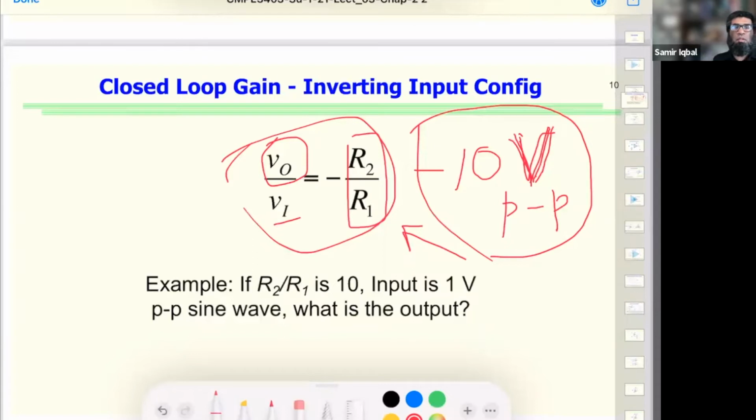We have got the control, but what have we lost? We have got the gain, but we have lost some accuracy, right? Because the resistors have their own tolerances, but we're still good enough. We'll still be getting a circuit which can give us a finite gain.